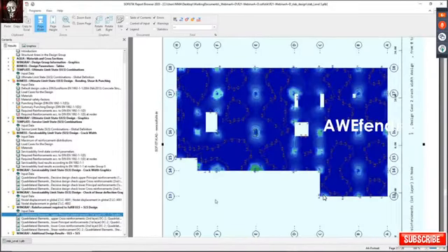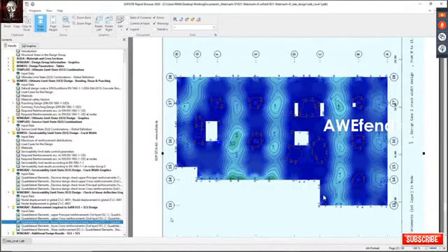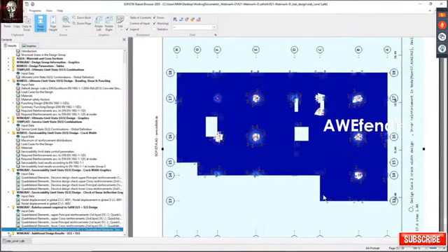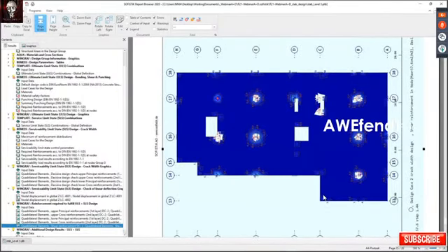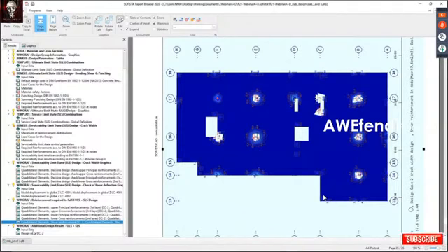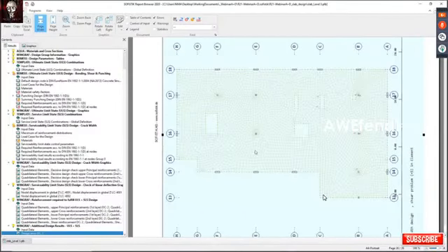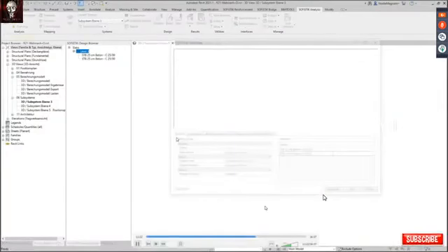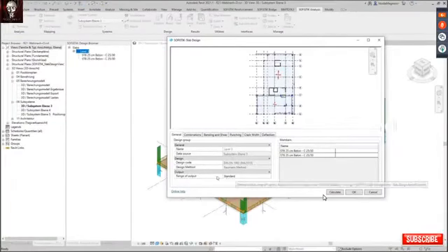Of course, at the end of the report, you have the required reinforcement in the different layers and in the different direction. Here, for example, as ISO areas, also shear reinforcement, if necessary. And finally, you can have, or you can ask for having an overview of points making problems where you have design errors. Here, small marked in red, for example. So this was, let's say, a very quick and standard output for my report.